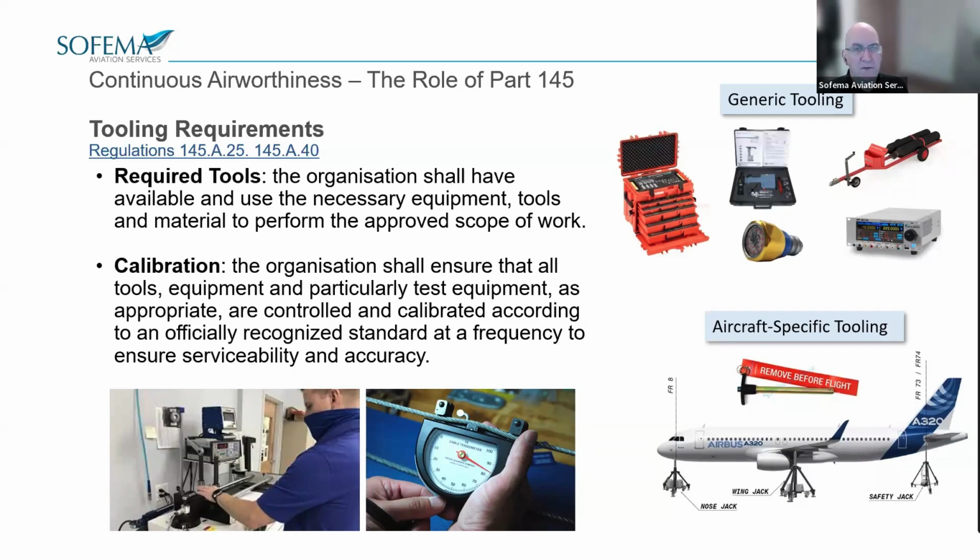An important requirement is for the organisation to have a proper tool control procedure for checking out and checking back in tools used in aircraft maintenance tasks. This is an important protocol to prevent tools from being left in the aircraft and causing foreign object damage. Tooling needs to be available at the point of delivery of maintenance. Any shortfalls and shortages should be minimised.